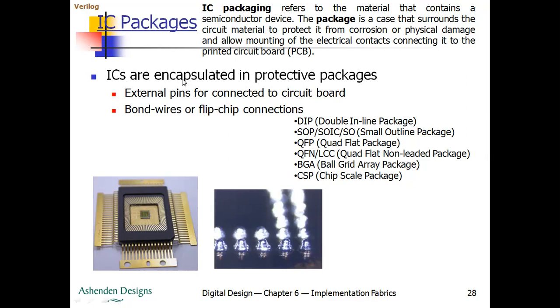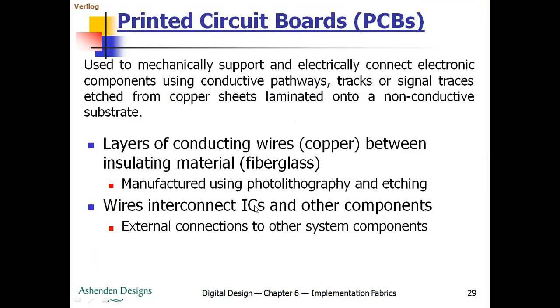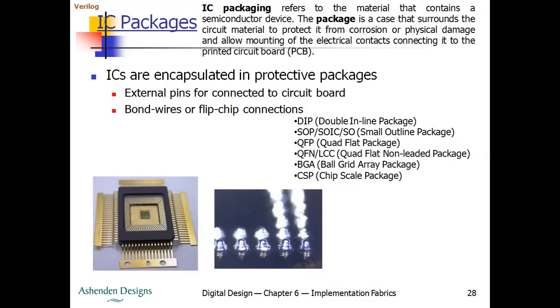These ICs are encapsulated or covered in protective packages, and we use external pins for connection on the printed circuit boards. You can go for either a bonded wire connection or a flip chip type of connection. We have figures to be explained, and I'll take those in the next class.